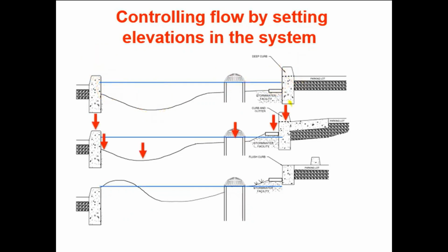In the second example, same thing. You need the curb cut elevation, splash block, raised drop inlet, low point of the retention area, high point of the retention area, which would act as a dam, and the top of curb for the adjacent parking lot. And of course, in the third example, the exact same thing. All of those points are going to be needed in order to explain how this system works. So quite frankly, this is a lot of spot elevations you have to put in. We're going to point out again the most critical one.